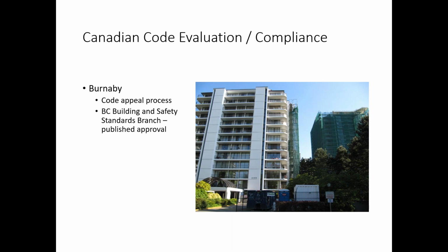And we found a project for that thermal spacer back in 2011 in Burnaby, which is a suburb in Metro Vancouver. And we proposed this spacer, and we actually retained a fire specialist, a building code consultant, to help us justify why we believe this complied with the building code. And what they said is that it is the same as other acceptable minor combustible components which the building code already permits. It doesn't explicitly name a fiberglass spacer, but it does explicitly explain that these minor combustible components are permitted. And that is actually a term, minor combustible component, in the Canadian building codes.